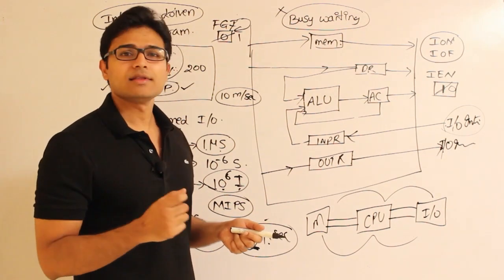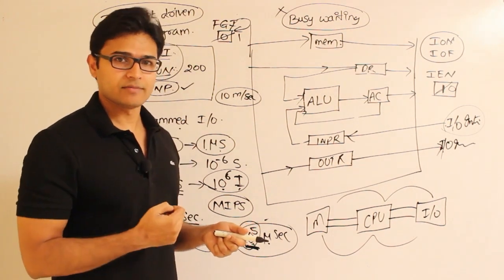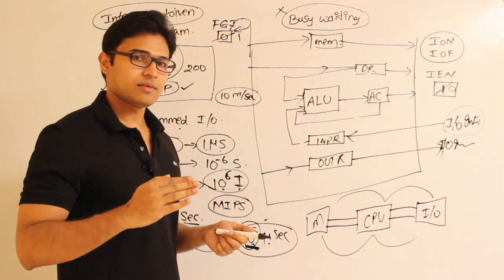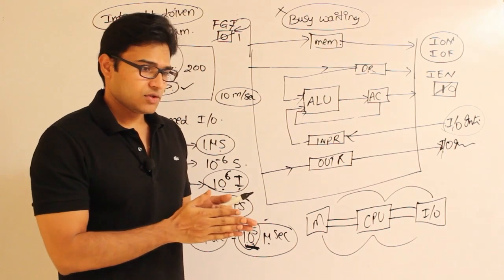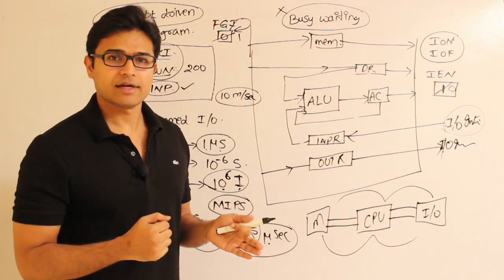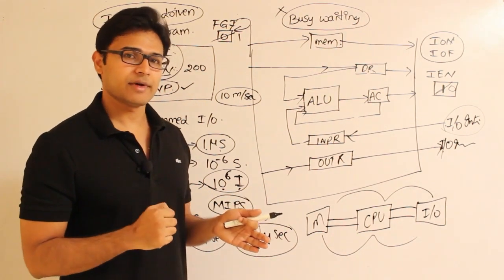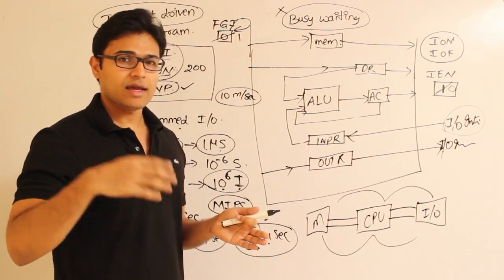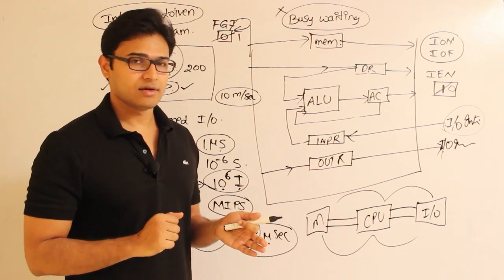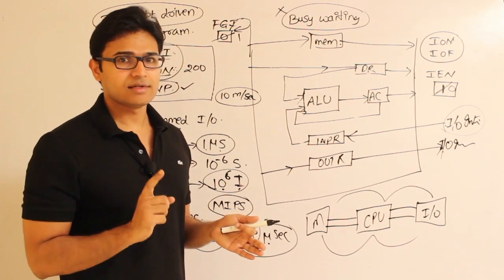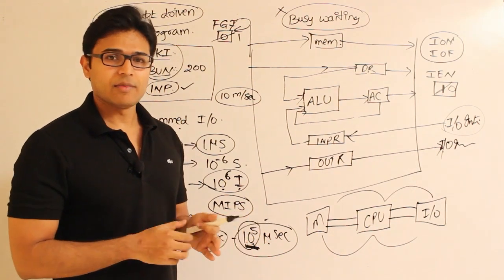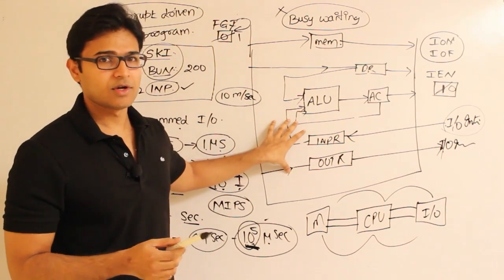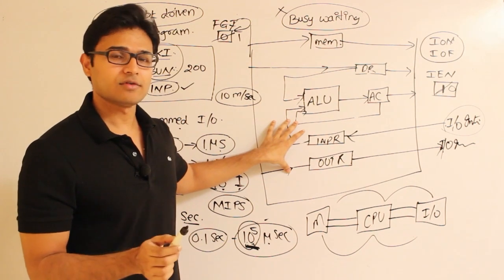The other one is that there could be a timer for every program. For example, if you are implementing round robin, then no program is supposed to execute more than, let us say, 1 microsecond. Then you can have an interrupt every 1 microsecond. The program being run will be interrupted, and the next program will be brought in and run. There are various reasons we can use the interrupt for, but in our simple computer, we are going to use the interrupt only for one reason, for IO.